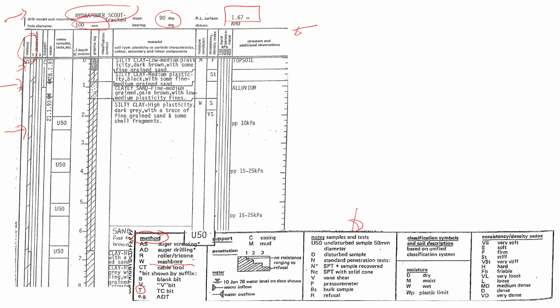So next, probably the most important thing that we'll see after that is water. This one will show you the groundwater table, the level at which the water was found. Actually, it's not very common, but here you see two different levels. They have two different levels because they did measurements at two different dates. You see, the first one was on the 21st of January 1993, so it's very old data. And the other one was on the 28th. So we have here two different levels of groundwater table. And let's move on to the right.